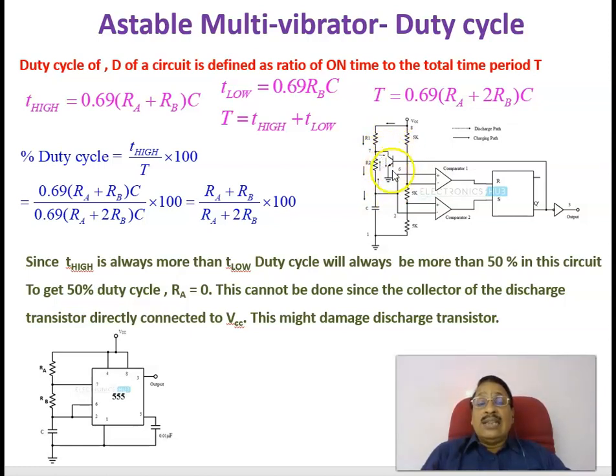The internal transistor gets damaged if you are directly connecting this point to the VCC. Therefore, that is not recommended. This cannot be done since the collector of the discharge transistor is directly connected to the VCC, and this might damage the discharge transistor.